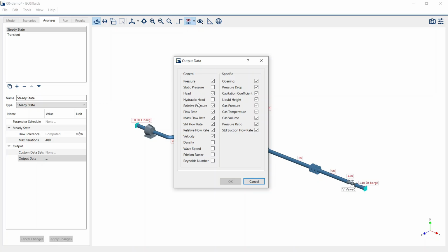Many engineers working in process flow also use the pressure not in actual pressure in bars or psi, but in head, so in a measure of elevation of the liquid. Especially if you have a system with elevation changes, you know from looking at your head data sets how much pressure, so head, you still have left for overcoming a certain elevation.